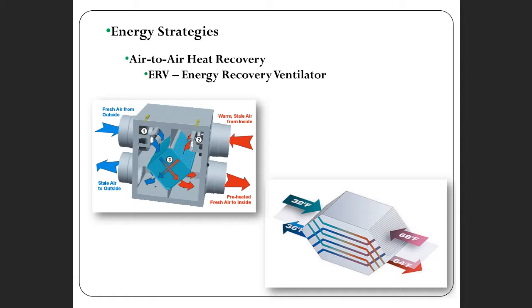Again, air-to-air heat recovery is a good energy strategy. We saw that in the picture of the passive house, right? So we've made the building envelope tight. We've reduced infiltration or uncontrolled air leakage, and now we have to have controlled ventilation to provide fresh air to the building occupants. And we typically want to try to do that with an air-to-air heat recovery system where we use that warm air that's being exhausted out of the building to preheat or pre-cool air that's being brought in to replace it.